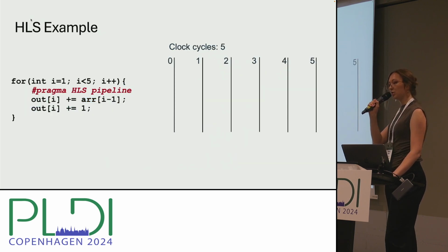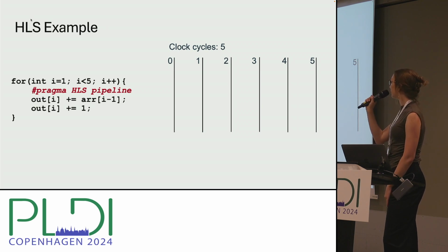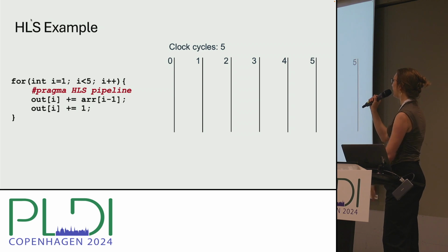And then I want to go into a middle ground example. HLS supports things called pragmas. You insert them into the C code and they tell HLS how to treat certain things. We talked a little bit about pipelining and unrolling before, but I just want to show why loops can be a middle ground for HLS given the existence of these pragmas.